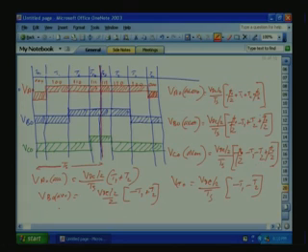So this way, our analysis shows that the space vector PWM is achieved by appropriately selecting the T1, T2 for a particular Vs, that is a reference space vector of particular amplitude and alpha. For different frequencies of operation, we can have different amplitudes, and alpha also varies when it traces the circular trajectory, but the frequency only varies. So this way we can find the space vector PWM can be implemented.